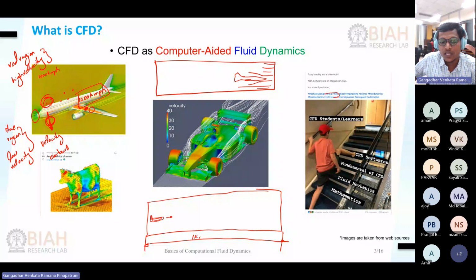This is my 1 kilometer space I designed and I'm trying to capture the movement of an aeroplane in this space. If you are doing that, you can move your aeroplane from here to this part, from point A to B, right? So you can only do the simulation from point A to point B and you can see the flow over the physics. But after coming to the point B, your aeroplane is going out of your focus area. I can say in the camera way, there is a camera seeing this particular area, the red box area. Okay. So this box is seeing some particular area. In the same way, in the simulations also, you need to capture some particular area to do the simulation.